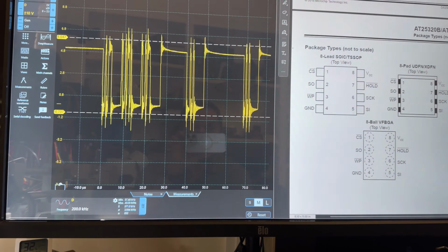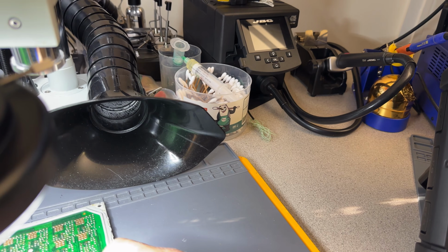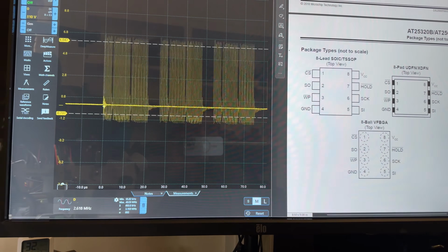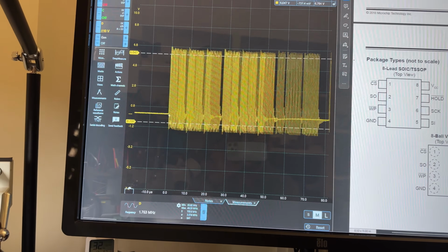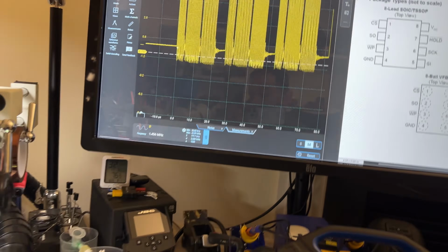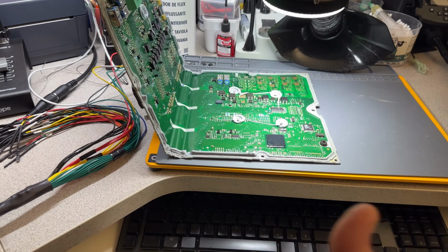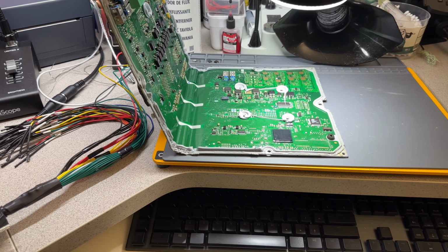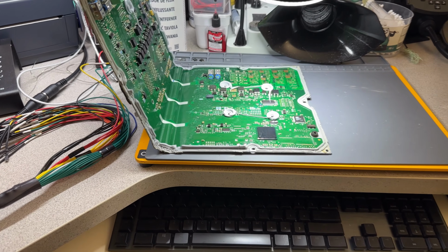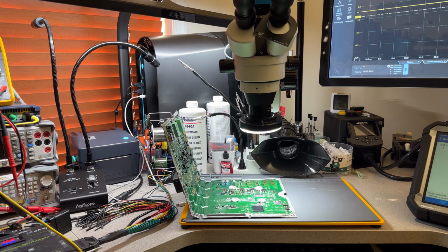Let's go over to pin 6, SCK, sorry. And we have the clock. You see? So this is all coming from the microprocessor to control the computer itself to make it work. Without the commands from the microprocessor going out, I don't care if you had the powers and grounds and everything, nothing else will work. And that is coming from here. So Zach, your computer is definitely not repairable. I'm sorry to give you the bad news, but that is all I can do.